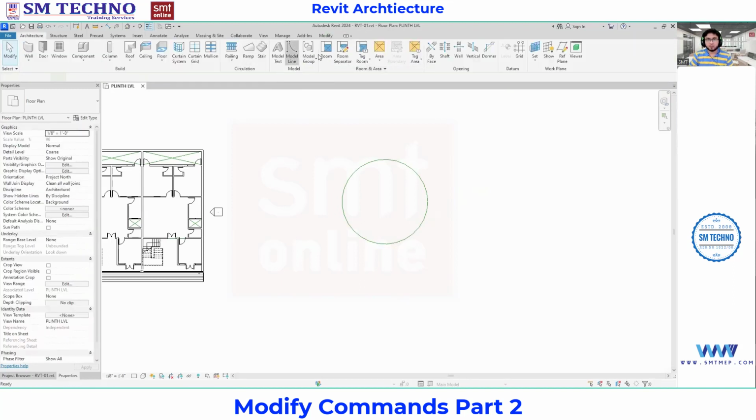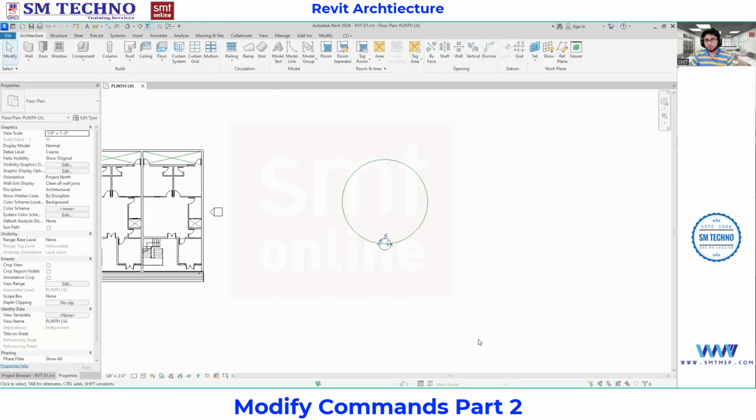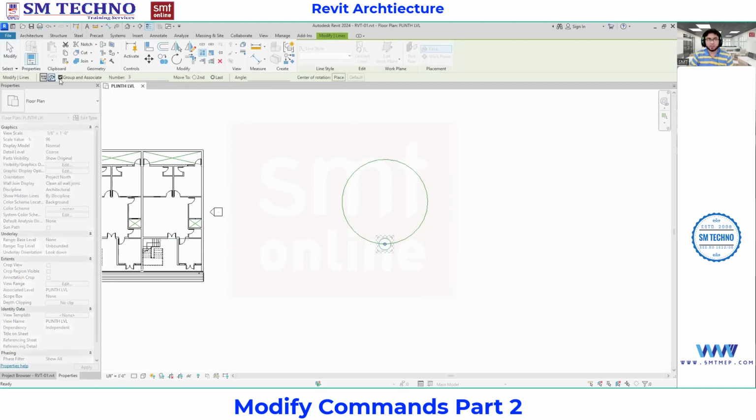I'll go with the circle again. I select the object. Now I'll go with the array. So in the array, the group and associate is on. How many items do you want? Something like 12 items, with the last angle of 360 degrees.